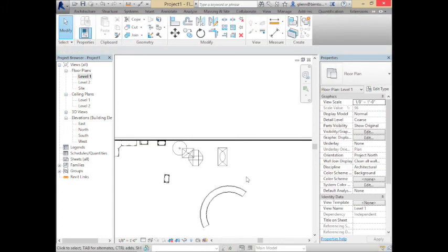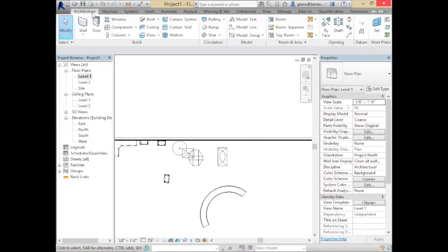Okay, you can create new drawing planes whenever you want to. Drawing planes, work planes are really just places you place things. And level 1 is a work plane. Level 2 is a work plane. All your levels are planes. Your elevations are planes. Your sections are planes. Anytime you define one of those cutting planes, it defines a plane that you can then pick. Okay. If you want to go through and create another plane just in some arbitrary place, you could always do that too. It's just really something, has no physical meaning. It's just a construction piece that'll help you work with things or draw things.